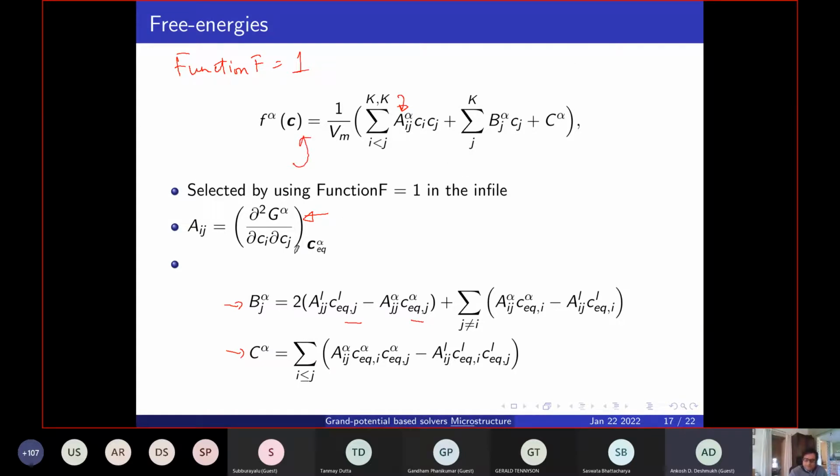Why is this already sufficient? It is because most of what relates the interfacial evolution to the local thermodynamic equilibrium at the interface is directly controlled by what is known as the Gibbs-Thomson coefficient, and the Gibbs-Thomson coefficient at leading order is just dependent on this. So for most microstructures, which are much larger than the capillary length, you are going to be dictated by this particular term.